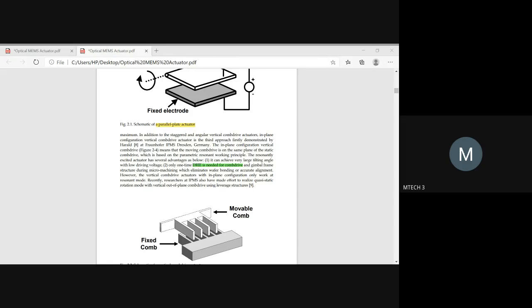If we are doing a surface micromachining process, then the etching happens at the sacrificial layer above the substrate. If it is bulk micromachining, then etching happens within the substrate. So this type of deep penetration etching comes into the picture in bulk micromachining with the help of DRIE. So this much you should be able to tell me. Is this clear?